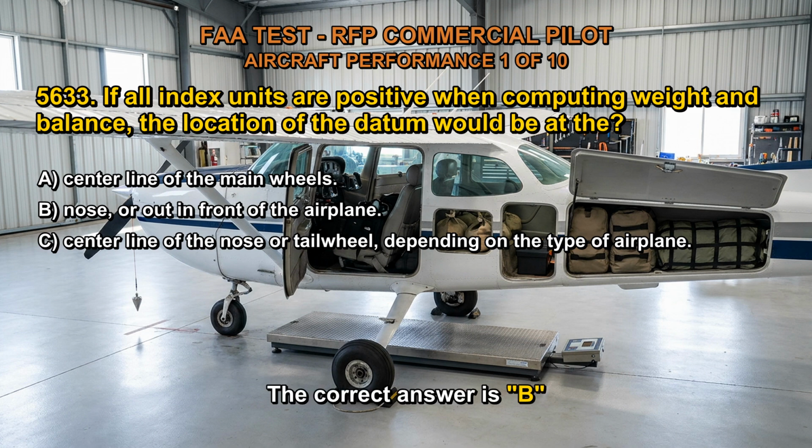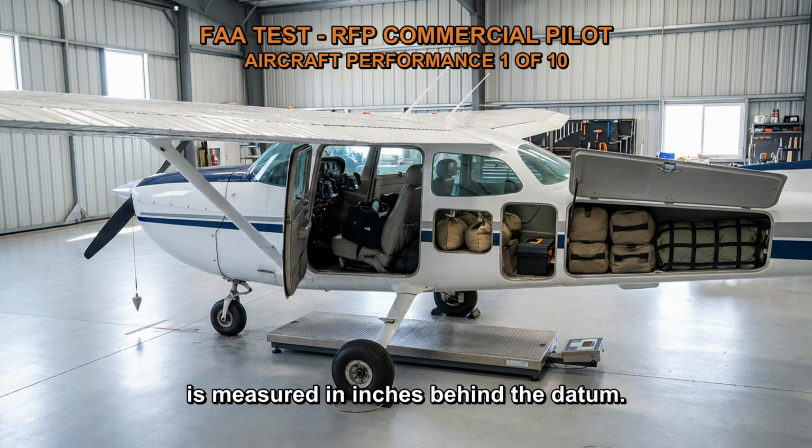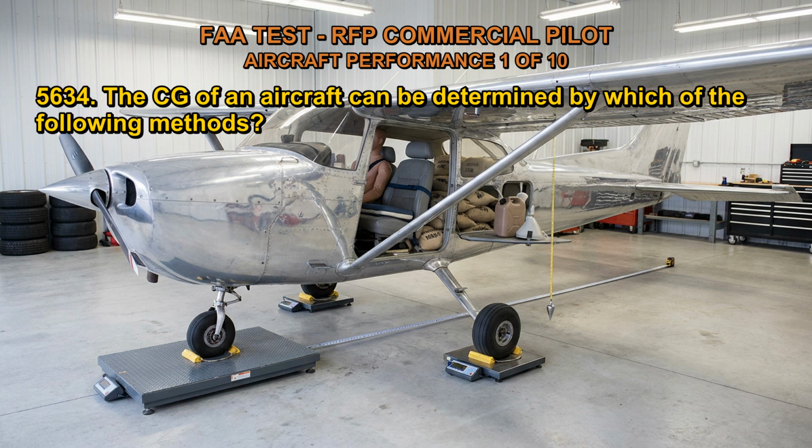The correct answer is B. In general, an aircraft location's arm, index unit, is measured in inches behind the datum. A positive arm indicates that the item is located behind the datum. If every index unit is positive, then the datum must be at least at the aircraft's nose.